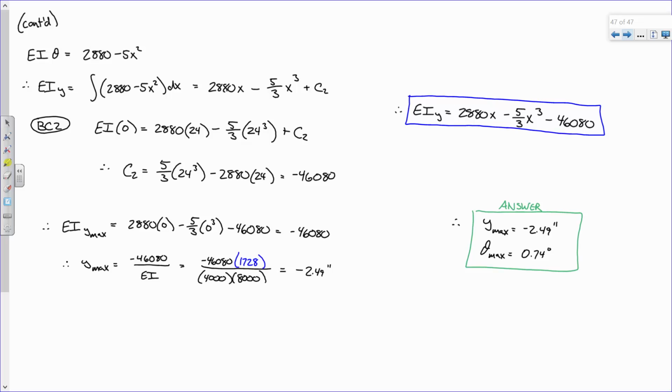Okay? And there are similar examples in mechanical engineering. If you're designing, let's say, a frame or a chassis for a car, put more elements into that frame so that each element picks up less load. And that's a very possible option, okay, in design land. So changing the geometry, changing the loading, changing the material, and changing the section properties of a member are really sort of the four fundamental ways that you're going to improve a design. So that's the big message I'm trying to get across to you as engineers.